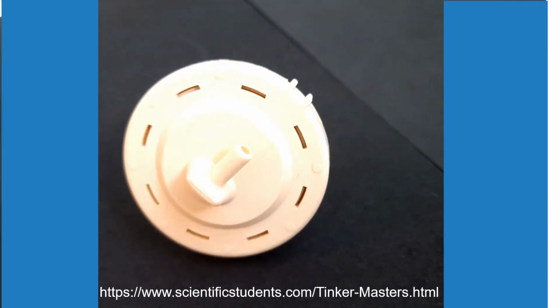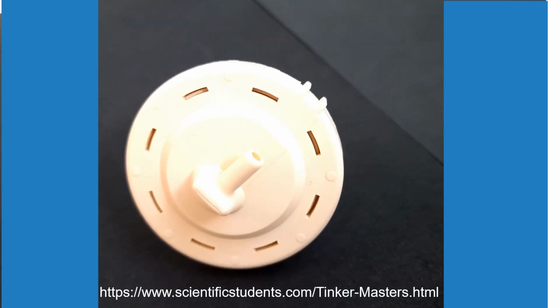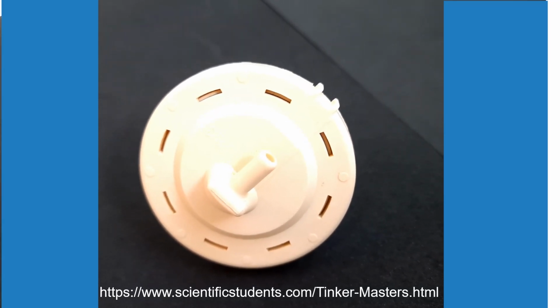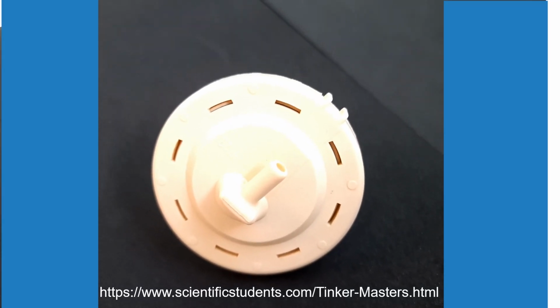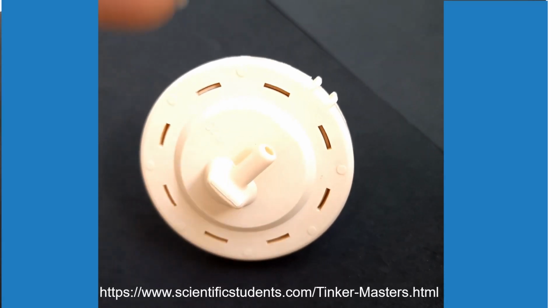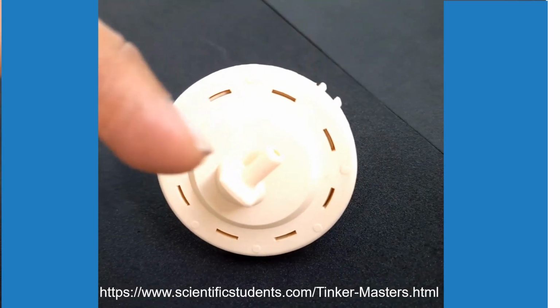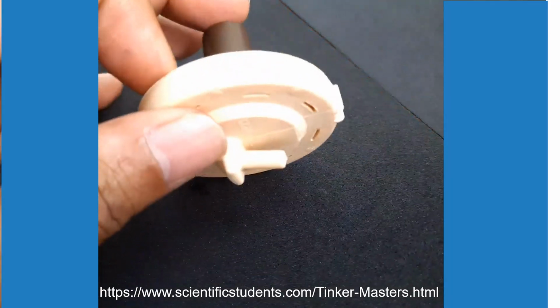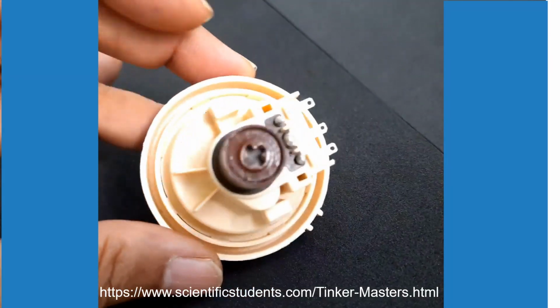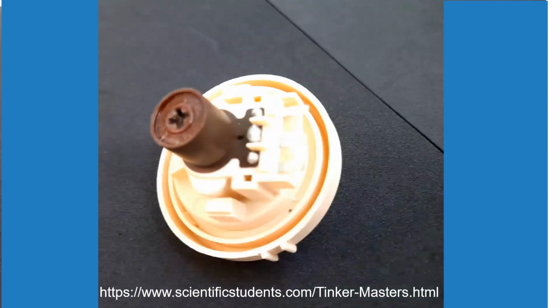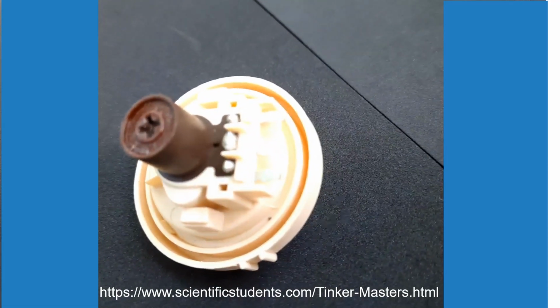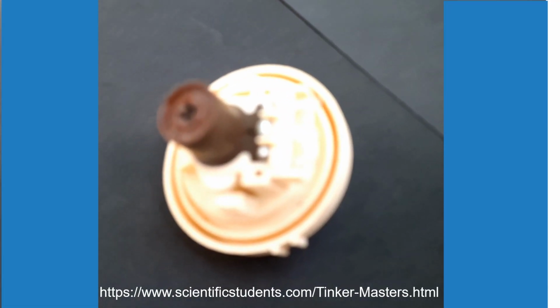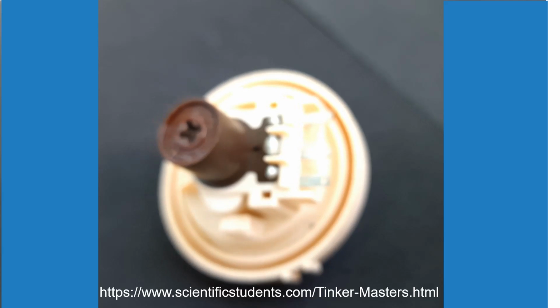The water may not go into the pressure switch, because the water column is raising slowly. So the pressure increases inside this tube, and because of that the pressure on the pressure sensor goes up. That's where the output signal changes accordingly. That's where the programming has been done in the control unit.